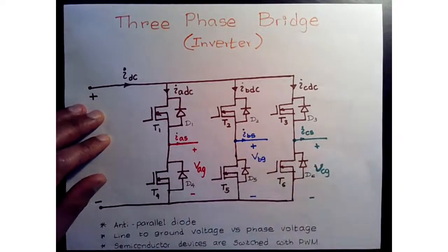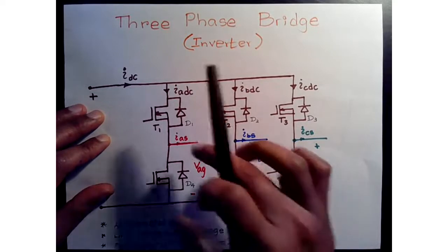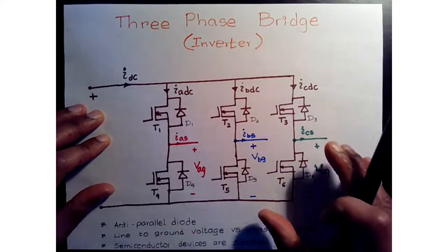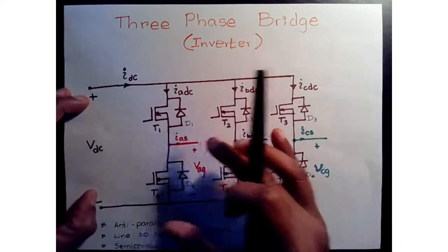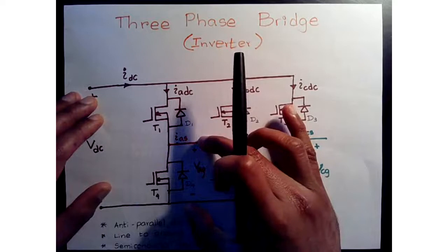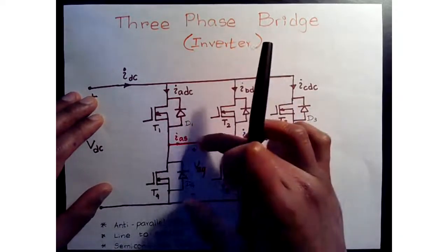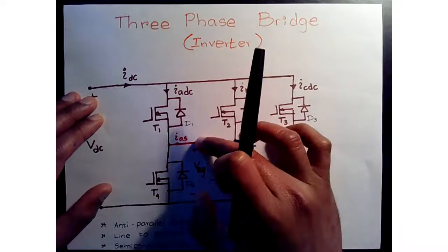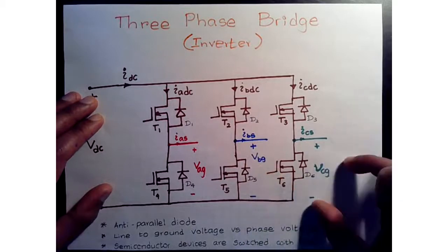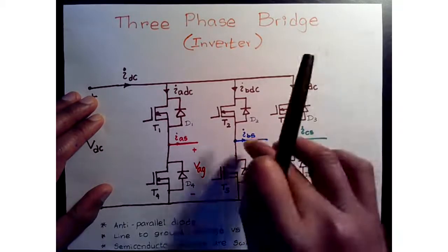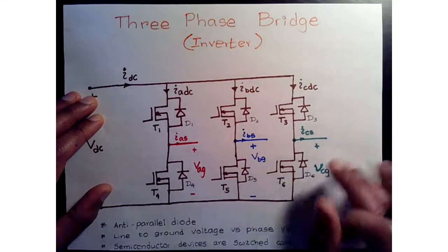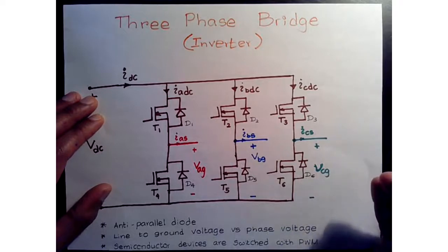Right now we have to think of 2 different voltages that we are going to see in our motor drive setup. Depending on whether you have a battery or a power supply, regardless of that, you'll have a voltage with respect to this ground bus that is applied to the phase. Then this phase goes and connects to a motor. That motor will have 3 phases, and for the motor, the connection of each of the phases will have its own closed loop where you can apply KVL to analyze the voltages.